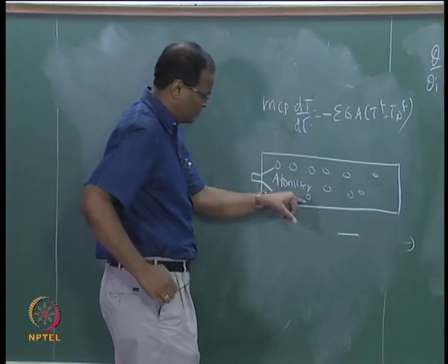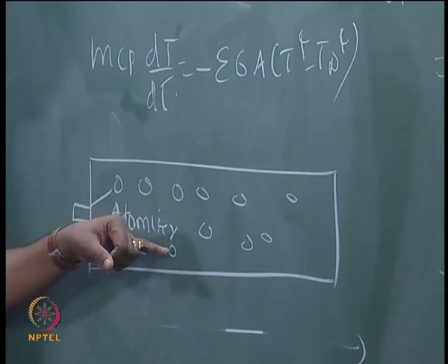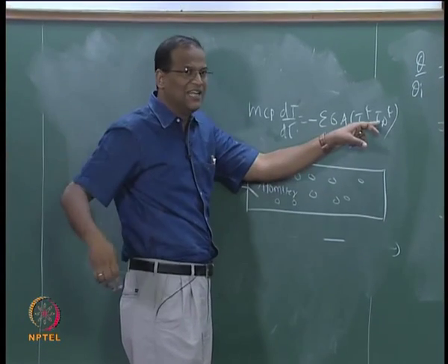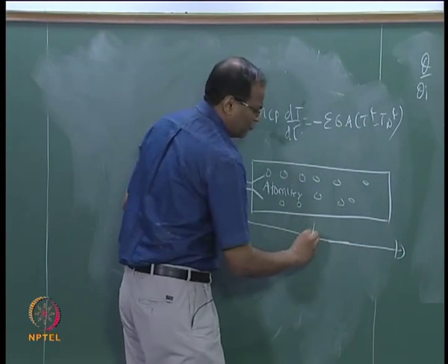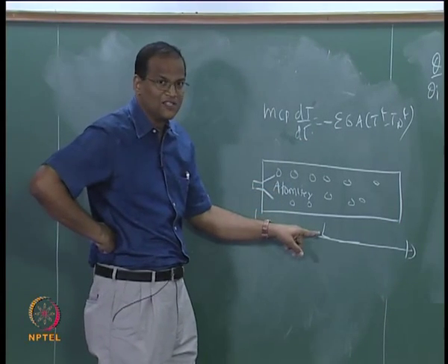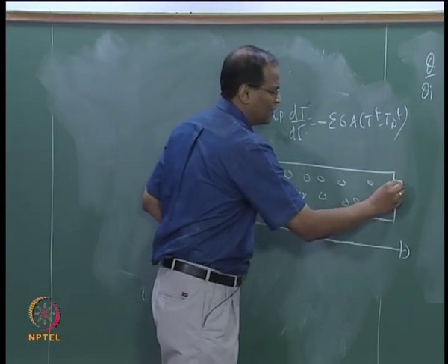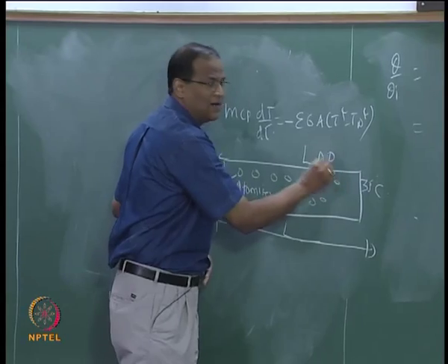Now each of these can be considered to be spatially isothermal, and if you know all the properties, and if the ambient is just outer space at 3 Kelvin, the cooling will be accomplished. So the design will be: what should be the length, if I know the velocity with which I push these drops out, such that by the time it comes out, if it enters at 60, I want it back at 35 degrees centigrade. So this is called an LDR, a liquid droplet radiator.